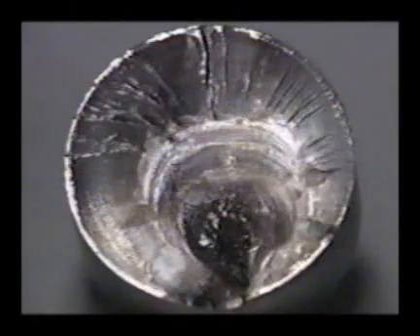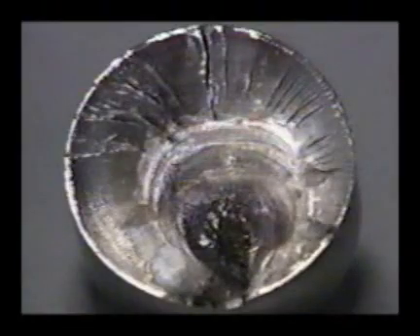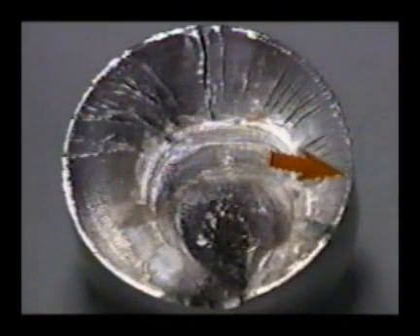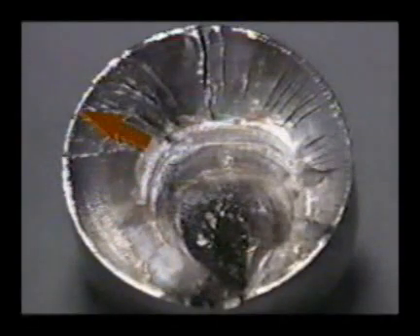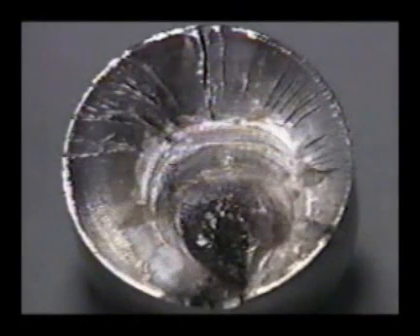Can you trace this fracture to its initiation site and determine if an abnormal stress raiser started it? You probably noticed beach marks and ratchet marks starting at a distinct subsurface line. This part of the fracture has a different texture. This rougher texture is actually a ductile or brittle pre-crack, an abnormal stress raiser that started the fracture. See if you can trace this fracture to its initiation site. What do you see there?